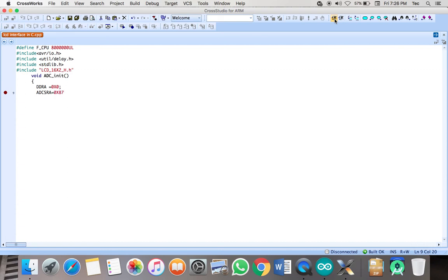Remember, in that code I wrote in assembly, I used 0x83 as our ADCSRA, and our ADMUX was 0x63, which was on port A3, but in this case we are using this, and that one was counting just up to 255, but now in this case we want to count to 1023, and our ADMUX will connect it to port A0.